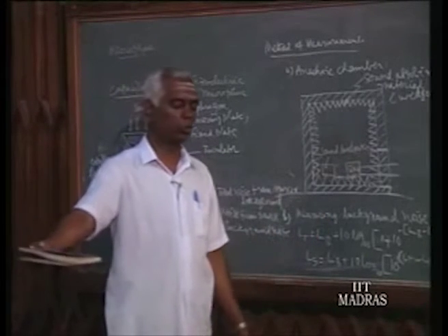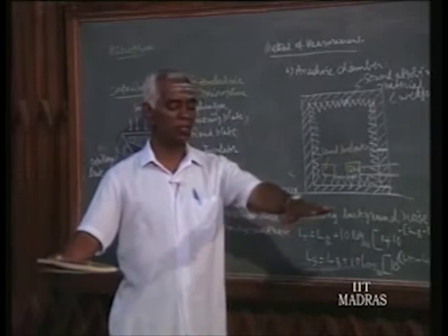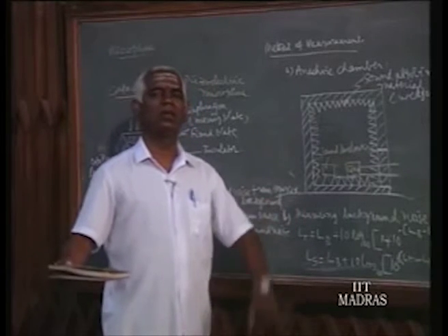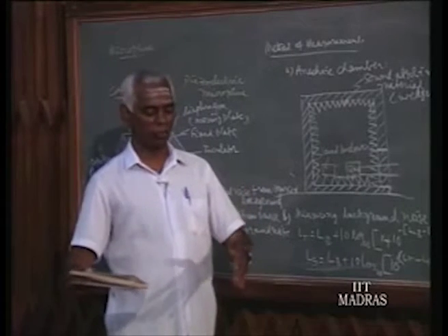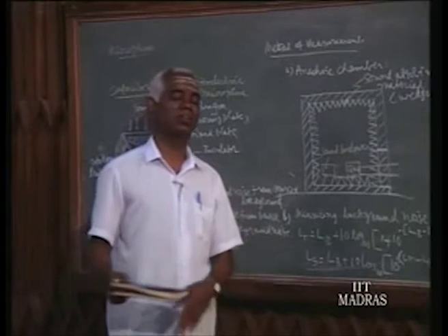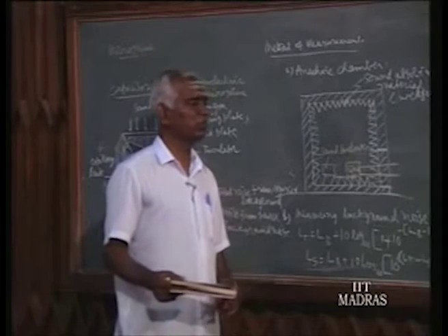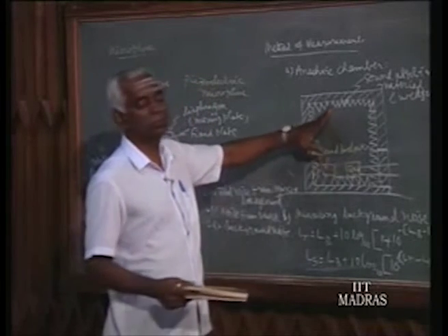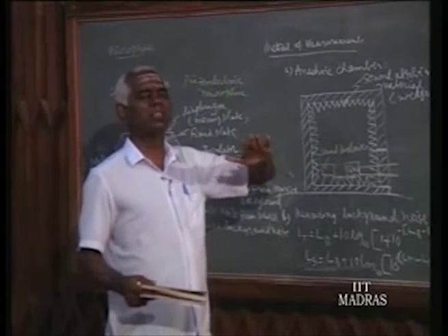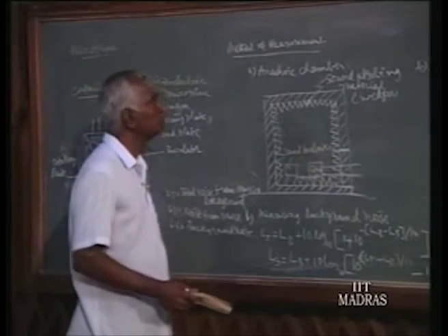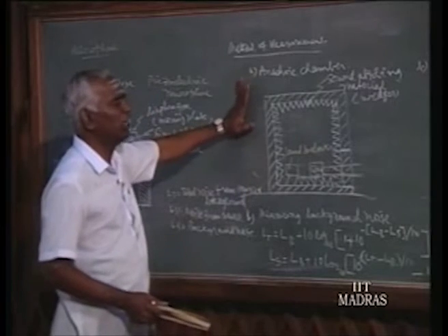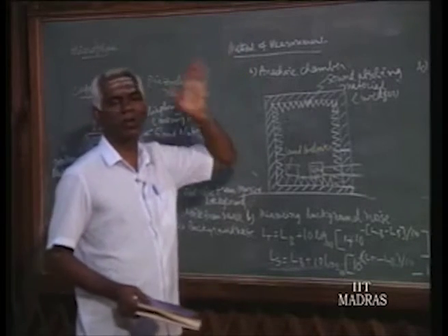So we should hold it like that only, and at a particular distance, because distance decides the amount of pressure variations. If we go to double the distance, the pressure variation is reduced to half. So in all measurements of sound, we are supposed to quote the distance at which the sound is measured. That's one thing. Secondly, I was telling there should not be any nearby wall and all.